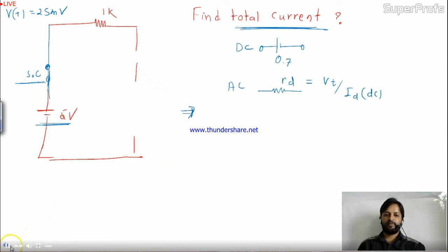When you replace them, your circuit will be, this is 0.7, this is the polarity, because the P portion of the diode, the anode, is given like this. So this is 0.7 over here, again 0.7, again 0.7, 4 times 0.7 actually.